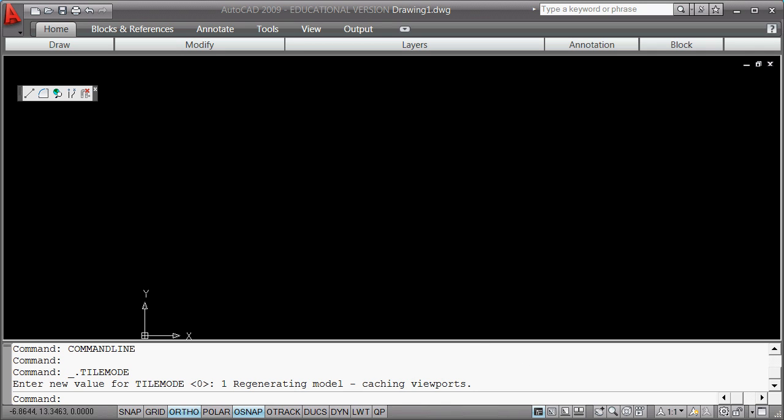Alright, this is the third 10-minute bit regarding object snaps, and now I'm going to show you why you develop the habit of a shift right click and why you use some snaps and not others, and why 2D and 3D are very similar but can be very confusing depending on how much screen space you have. You see a lot of you drafting in one window and not seeing yourself in 3D. You're looking down in what's called a plan view, the top view, in a parallel projection. We'll talk about perspective and parallel projections, but that's what's going on.